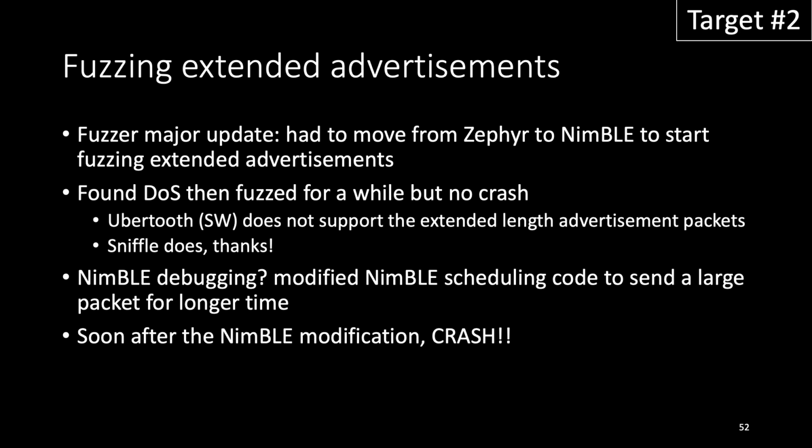And it turns out when I debugged NimBLE, NimBLE actually does not allocate enough time to send really long length advertisement packets. So I modified NimBLE, and then I found a crash almost right away, which led to an RCE bug.